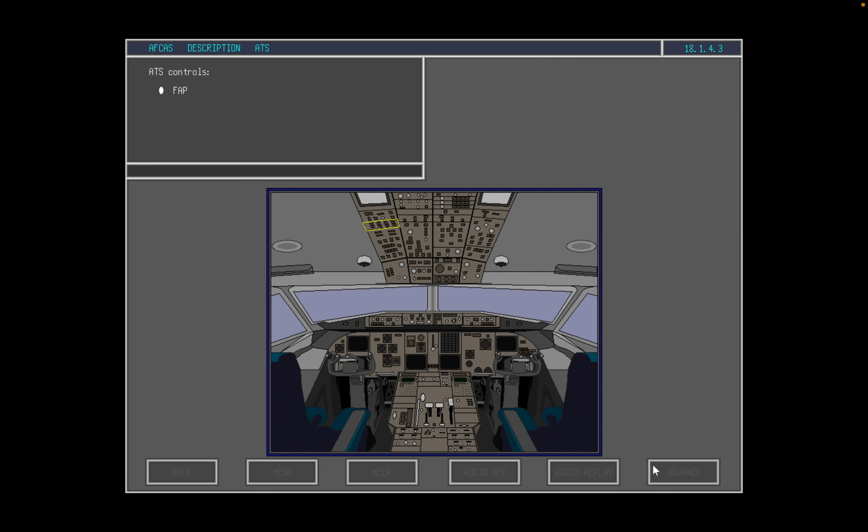Controls for the autothrottle system are located at the flight augmentation panel on the overhead panel, the flight mode panel, the thrust rating panel, and the thrust levers. Indicators associated with the autothrottle system are displayed on the flight mode annunciator on both PFDs, the primary page of the MFDU, and local lights.